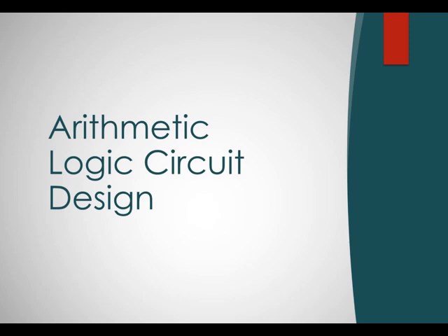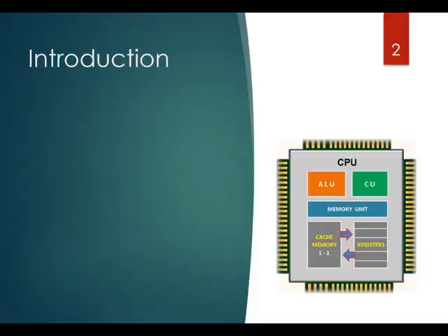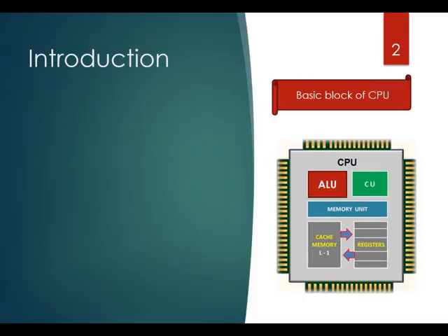Hi all, this is a video for arithmetic logic circuit design. Okay, so ALU circuit is very important because it's a basic block for the processor. And it is basically a combinational circuit. In other words, ALU does not contain flip-flops because flip-flops are only for sequential circuits.